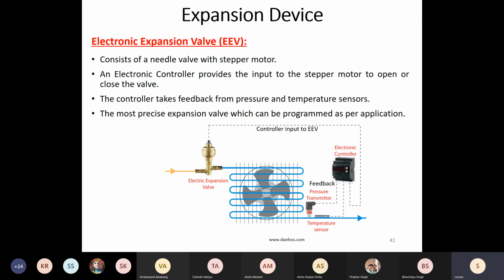which will take feedback from multiple sensors. So what is the feedback? Just like in your TXVs or TEVs, whatever you want to call it, you have a feedback in terms of degree of superheat. Now, the mechanical design of the TEV ensured that we always get the opening area proportional to the degree of superheat. That was the ingenious design of the valve.